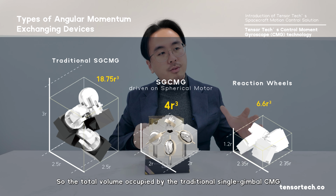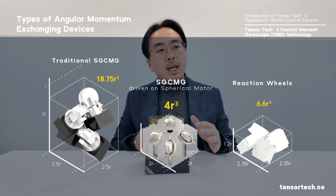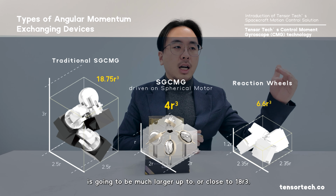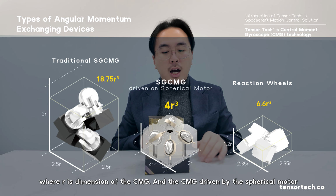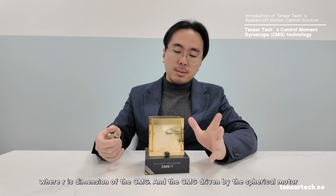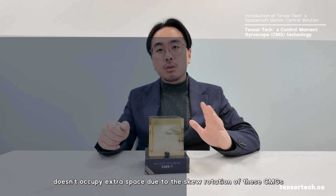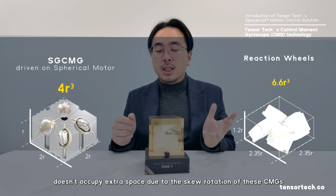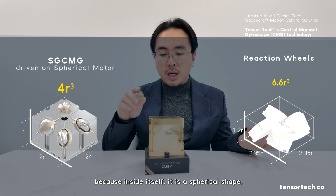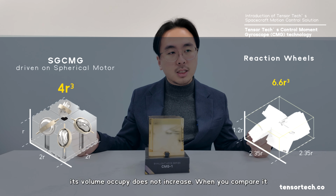So the total volume occupied by the traditional single-gimbal CMGs is going to be much larger, up to close to 18 r^3, where r is the dimension of the CMG. And these CMGs driven by a spherical motor don't occupy extra space due to the skew rotation of the CMG, because inside itself it is a spherical shape. So when you tilt something spherical, its occupied volume doesn't increase.